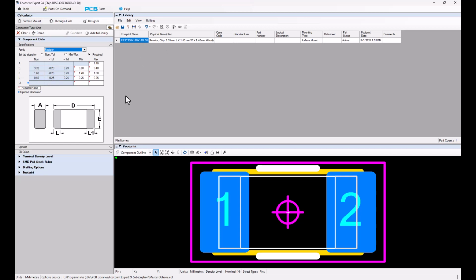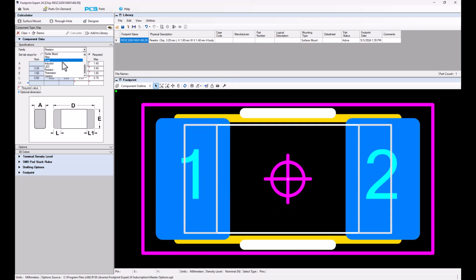The thing that is unique about the resistors and capacitors is that you want to use the same 0603 or 0805 or 0402, you want to use the same pattern for all your capacitors. But the difference is the height. I'm going to pick a capacitor for this one. See, I have a 1.4 millimeter height for this 1206, but the heights are all over the place.